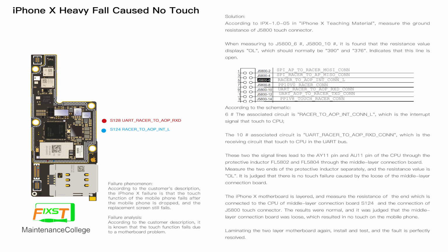First of all, when we meet the no touch problem, the first thing we need to do is change the LCD to have a test. In this case, after changing the LCD, the problem is still there. It's confirmed that the problem is a motherboard problem. When we meet this problem, the first thing we need to check is the resistance of the connector, right? This is a no touch problem. So first we need to test the resistance of the touch connector.